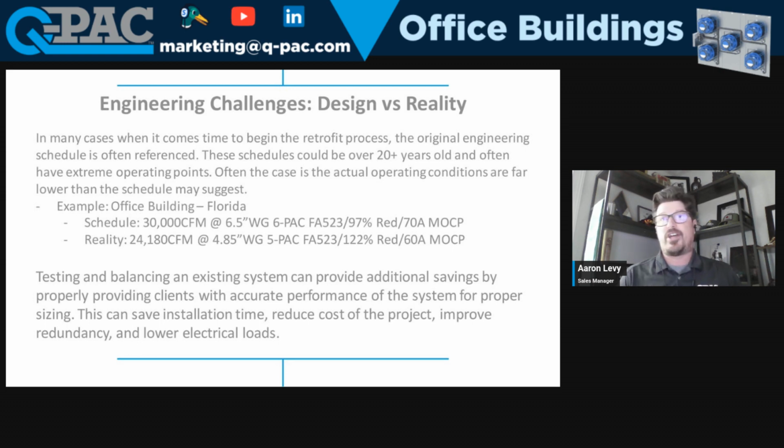For a few thousand dollars to have that system, to get an idea of what the system's actually running versus what's written down on a piece of paper, can save them 2 or 3 fans in the grand scheme of a system, especially the higher you go up. So in essence, the test and balance will normally pay for itself, by being able to design a system that's more geared for what they actually have versus what they think they have.